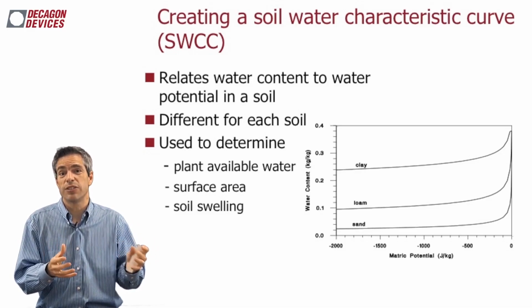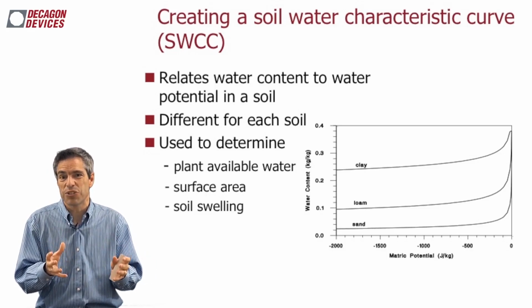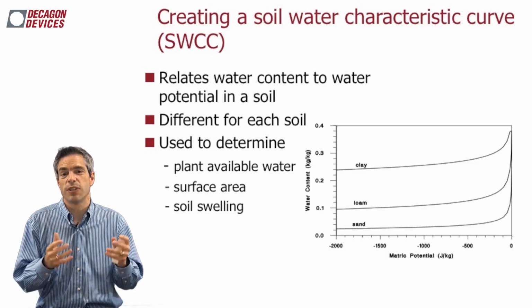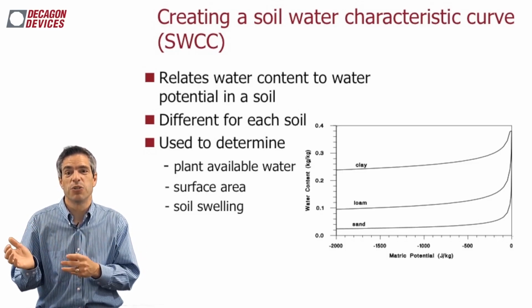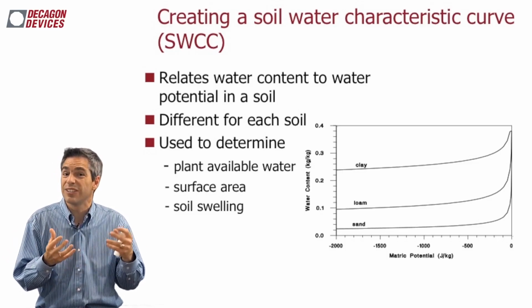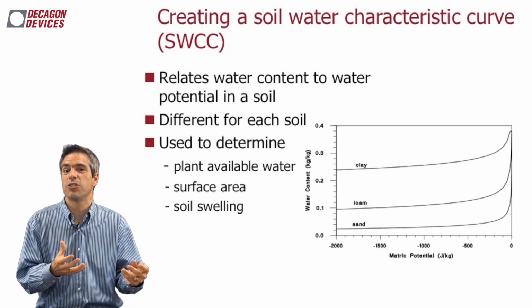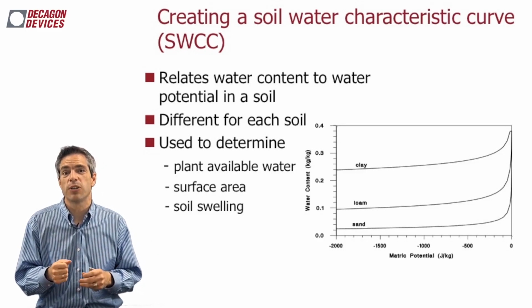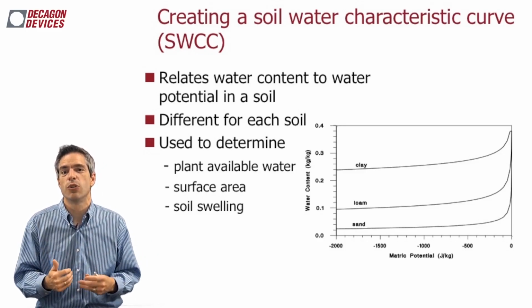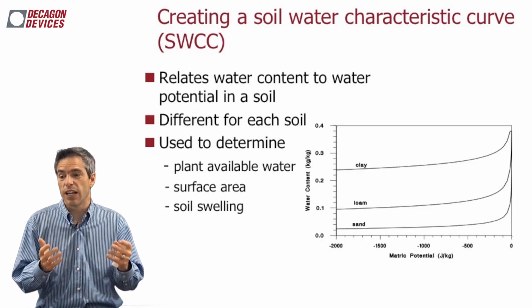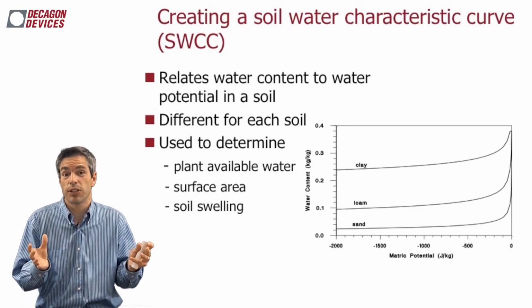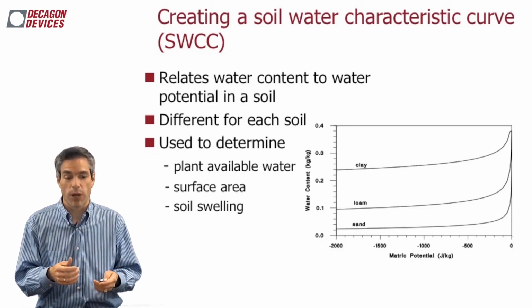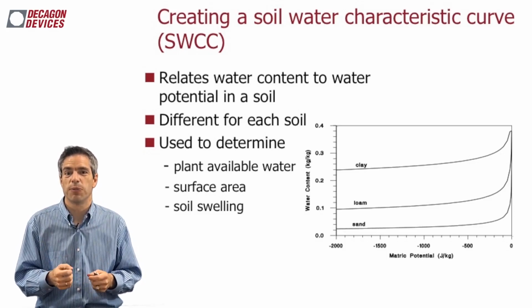We have shrink swell clays down there, and it was interesting that a lot of foundations were being torn up because of this problem with swelling soils. Using this technique of SWCC analysis, we can actually determine beforehand, before we ever build on that soil, if it's going to be a swelling soil and what we need to do to mitigate those effects. I had a friend whose house cracked completely in half. They probably wish they had made that measurement beforehand.